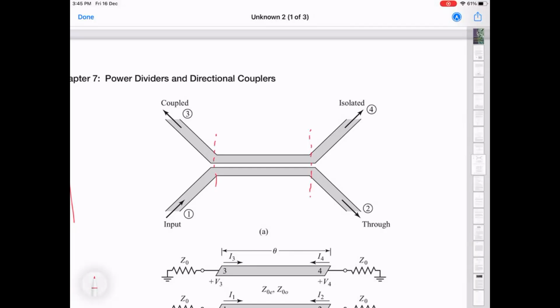You need some way to interface to it, right? And that can only be done if those transmission lines are taken further away, because practically you need to put some connector. And here, if you notice the width, this of course is a cartoon, but still, the width here is not the same as the width here, because this width here is basically for 50 ohms, that is, whatever matched port you are putting here.